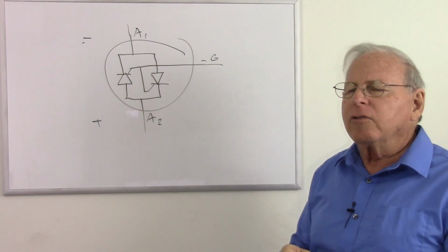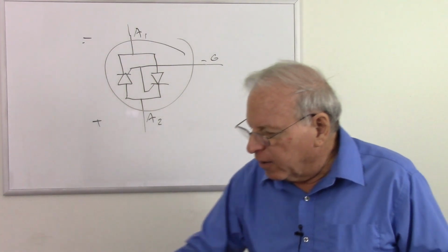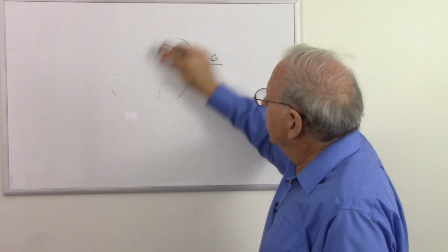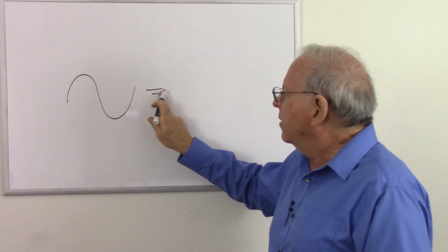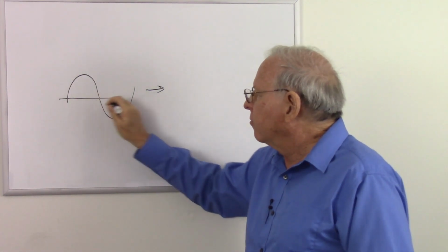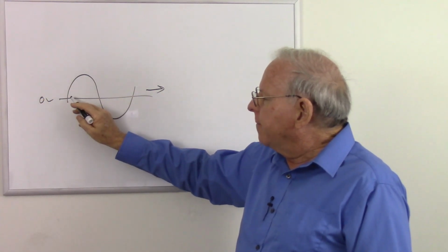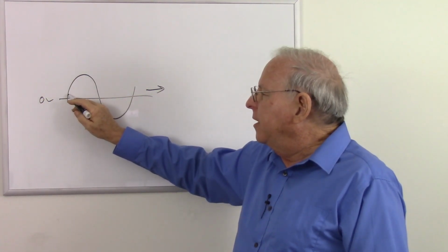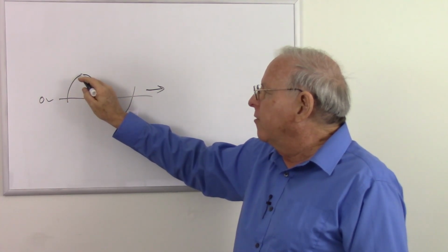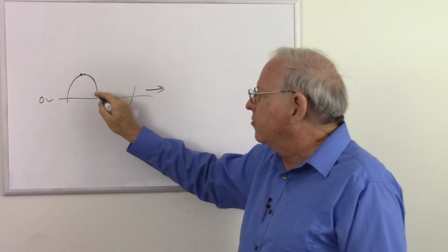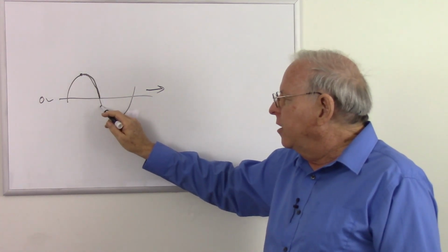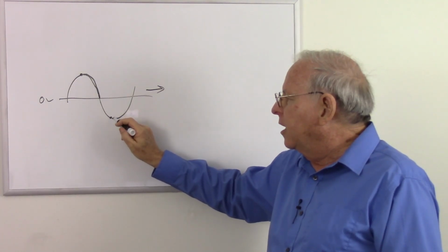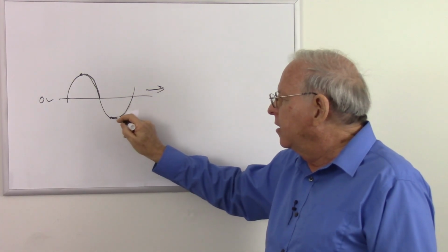These are used in light dimmers where, if we look at the alternating current going to a light bulb, this goes through a circuit such that, here's our 0 volts, such that we bias the triac, but nothing happens until we trigger it at some point, and then it conducts for the rest of that cycle. But when it hits 0 volts, it stops conducting. And so it doesn't conduct until we trigger it again, and then it conducts until it hits 0 again.